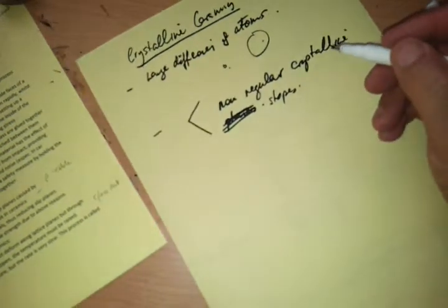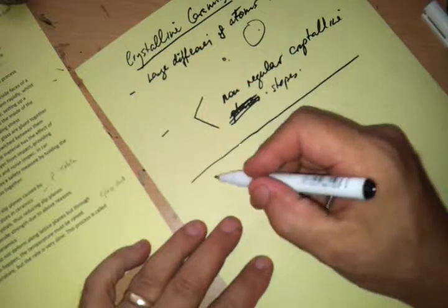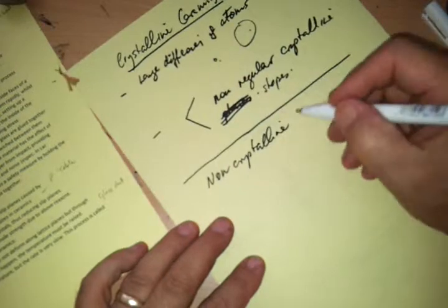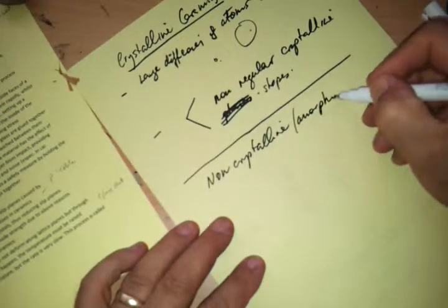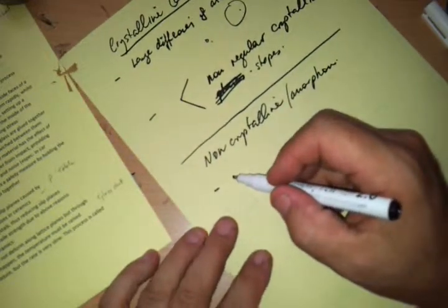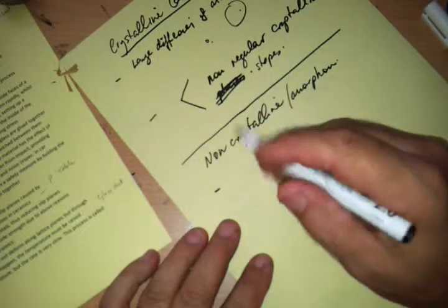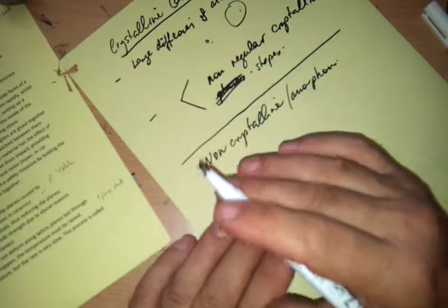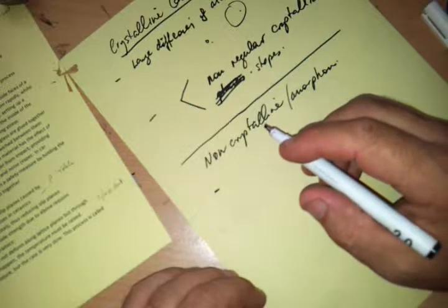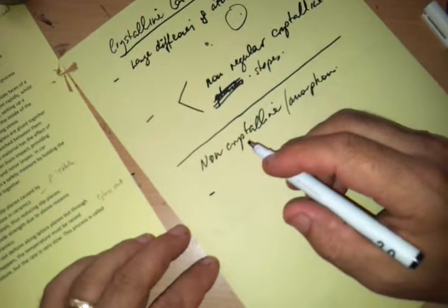Okay, mechanical properties of non-crystalline ceramics, which are the amorphous ceramics. What are the mechanical properties? In the case of glasses, they don't deform along lattice planes very much, but they deform through viscous flow, because when they cool, they remain in liquid form, I should say, even at very low temperatures.